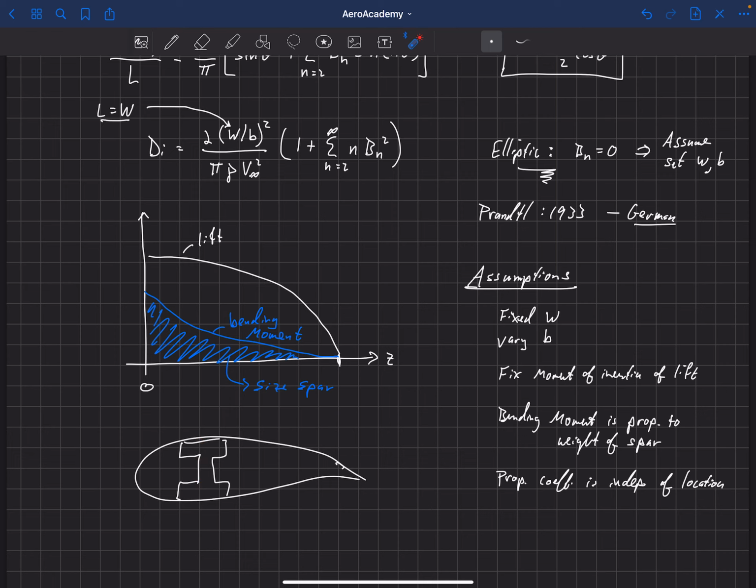So if you're going to apply the same airfoil across the entire wing, what this all comes down to is that he basically assumed that the chord was constant. Really, the analytic solution he comes up with here is only true for rectangular wings, unless you're able to keep the thickness of the wing the same even if you're changing the chord. So that's a really important thing.